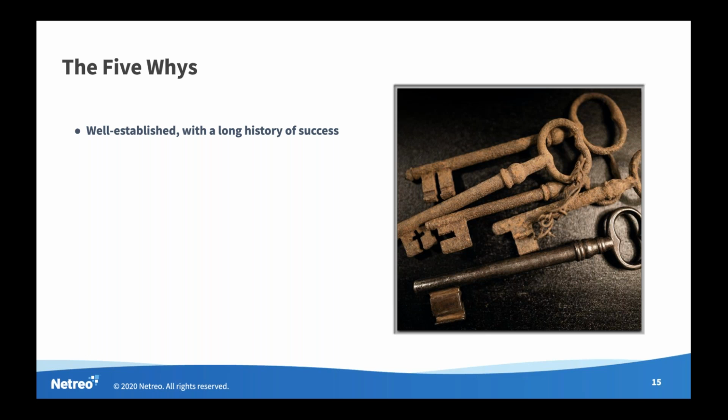It allows you to get beyond the technical cause of the problem and get to the true root cause of the problem. So in its simplest form, it simply means asking, "Why did that happen?" 5 times for every problem, although it may take fewer or more to get to the real cause of a problem. But it's often not at all what you expected it was. Very often what appears to have been a technical issue was originally caused by a human factor or a process failure.